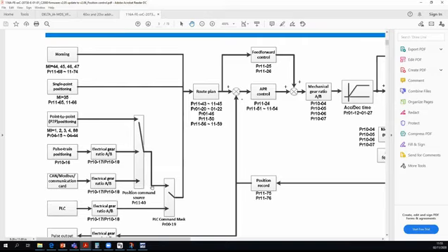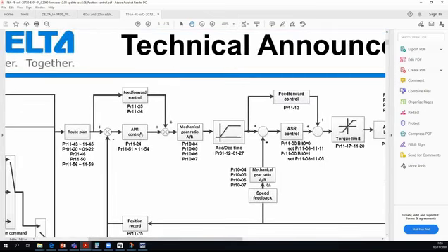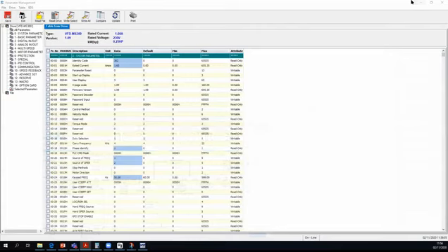And of course, you need to set the source of position command, 1140, you need to set to 0, so that the drive knows what it's actually looking for. And then you have a number of different parameters which you can set to control how strongly the drive reacts to different configurations. Okay. So I hope this answers the question.